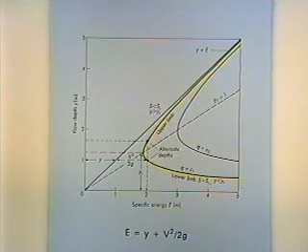What happens if you change something? A good example would be changing the bottom slope, the longitudinal slope. If we were in a laboratory, we could imagine looking at a flume or a channel. In our laboratory here at A&M, we've got such a thing, a variable slope, and you can jack up one end and change the slope. Of course, when you make it steeper, the water flows faster, you get a higher velocity and a lesser depth. In some ranges, a change will result in a bigger change in the velocity head than in the depth. In some other ranges, vice versa.